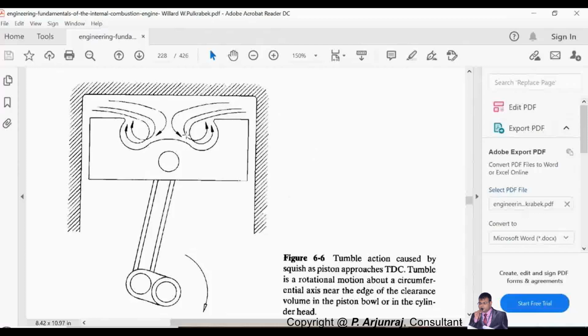Again, now I'm telling you with respect to the diesel engine. With respect to gasoline, the terms will vary. In the case of gasoline, it is both air and fuel. But now I'm discussing the diesel engine, then I will explain about gasoline. So when I talk about the diesel engine, the tangential flow of air is coming into the chamber, which is above the piston bowl.